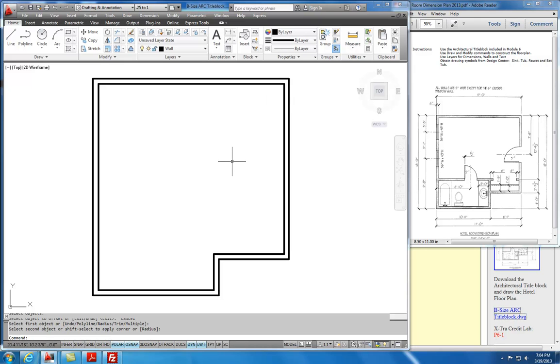So now we have the exterior walls completed, and we're going to do the interior walls. We're going to work on this area right over in here. This is a closet, and we'll locate the wall that the doors are mounted to, a distance of 2 feet 7.5 inches to the center from this outside line here. Actually from the center of this line here, so we'll say offset 2 feet 7 dash 1 divided by 2, enter.